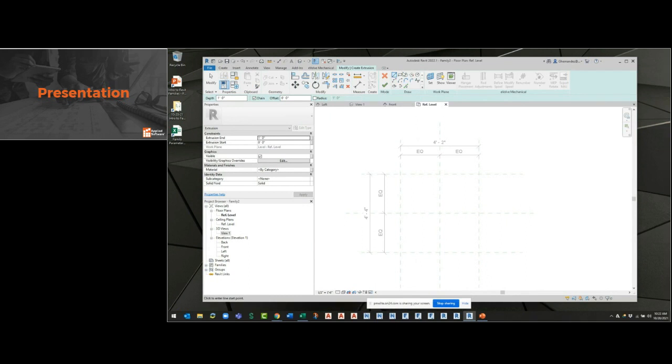Right? So I would use the rectangle command here and use my intersection to intersection. It will pop up these what we call alignment locks for the sketch. So if I lock this sketch to the actual reference planes that I'm drawing to, watch what happens. When I finish this out, this is the key to this sketch mode thing. If you see the green check or the red X, you need to do one or the other to get out, right? So when I'm done with this, I need to finish this out.